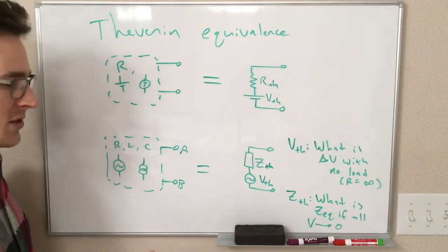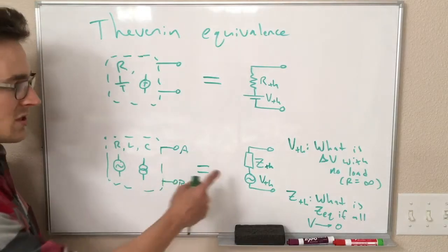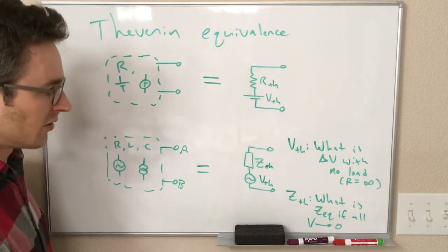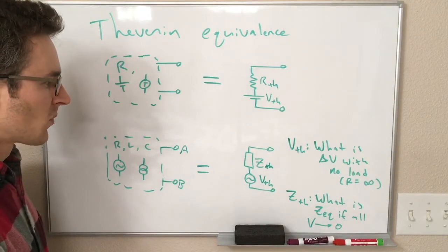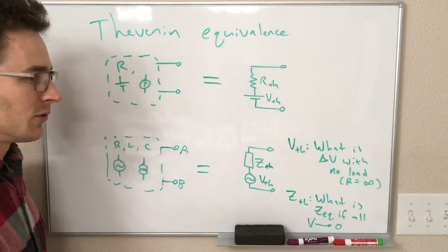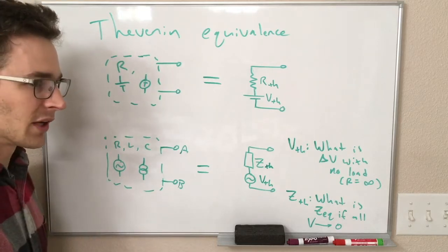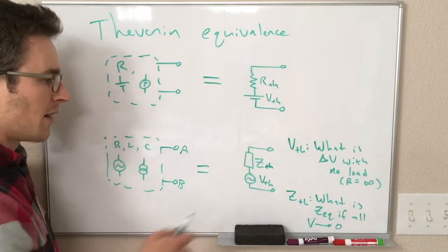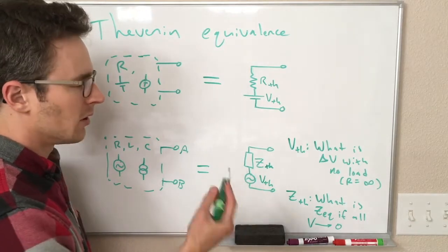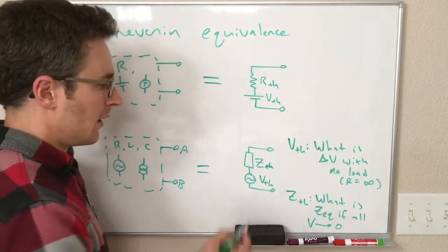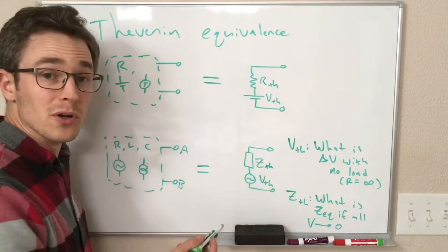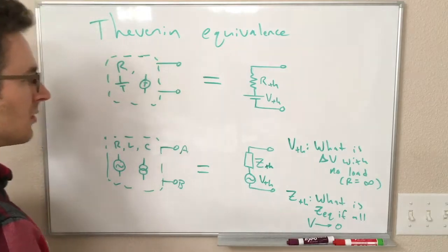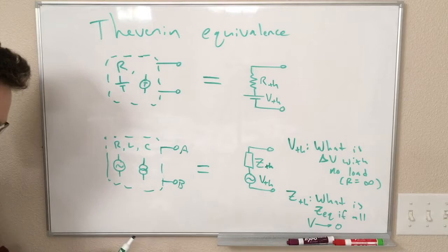Certainly, if you're analyzing a circuit for a bunch of different loads, it is much easier to figure out the equivalent and then just treat it as a little 2 impedance voltage divider to see what's going on. And also it means that in general, if you have complex circuits, you can predict how their output is going to change under different loads if you have some model. For something like a power supply, you would call this Z the output impedance, and that is an important characteristic of different instruments. So yeah, this stuff definitely matters.